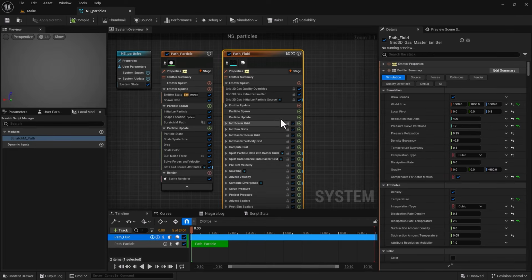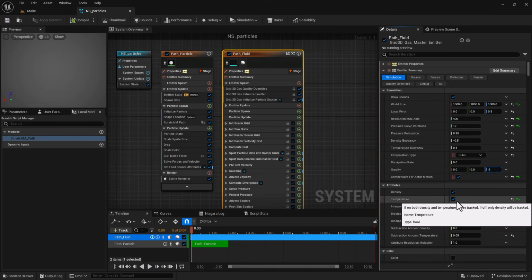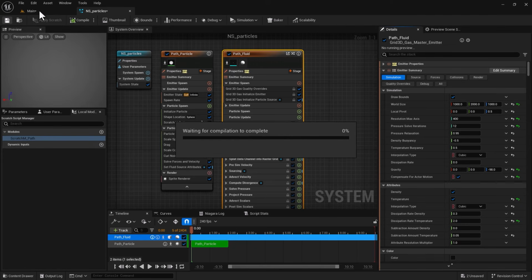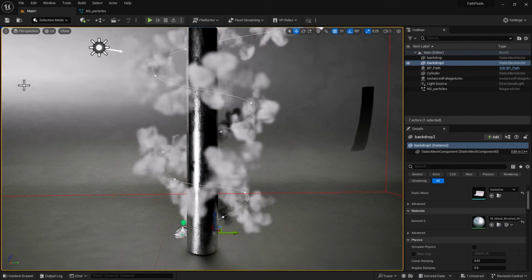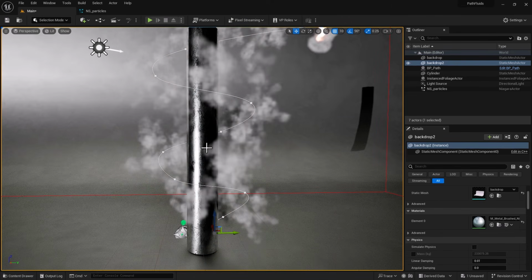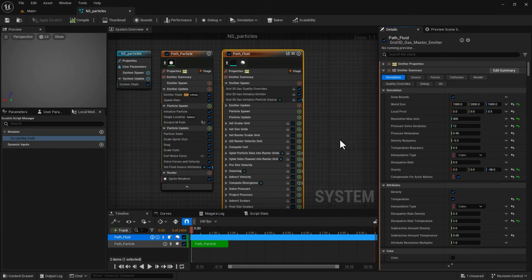But chances are you want to get more of a sci-fi look, let's say spell-looking type of magic lightning type of look. In that case, you have to go and tweak things. Now I noticed that the fluid rises really quickly, so maybe minus 98 instead of 980 would be a good value. Let's go and check. Yeah, as you can see, it's not going to evaporate and rise so quickly. Although I must say that was a bit too low.